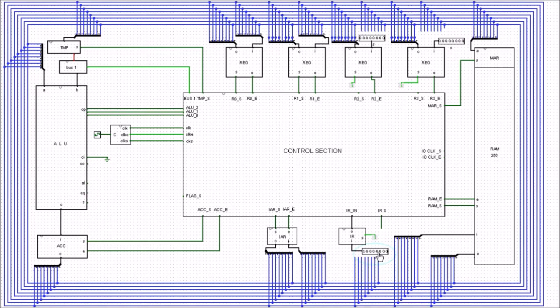Now the next 2 bits refer to our reg A, and the next 2 bits refer to our reg B. But remember, reg A just refers to the 4 registers here, and reg B again just refers to the 4 registers there as well. So what we want to do is add the 2 numbers together. This register here is going to be given by our 01, so that's going to be our register 2. So it goes register 0, 1, 2. And this register here is going to be our register 3. Okay, so it goes 0, 1, 2 and 3.